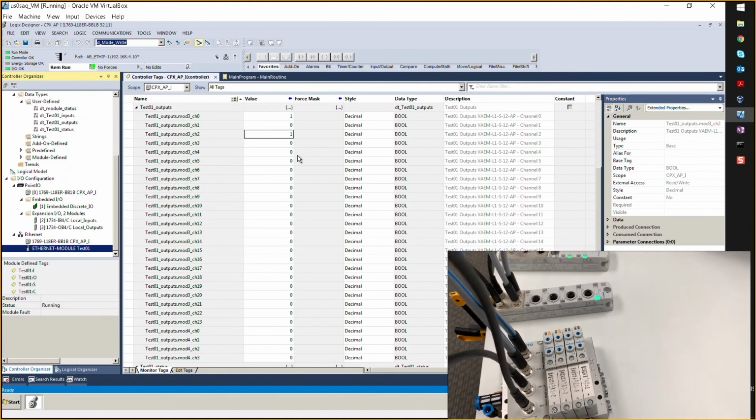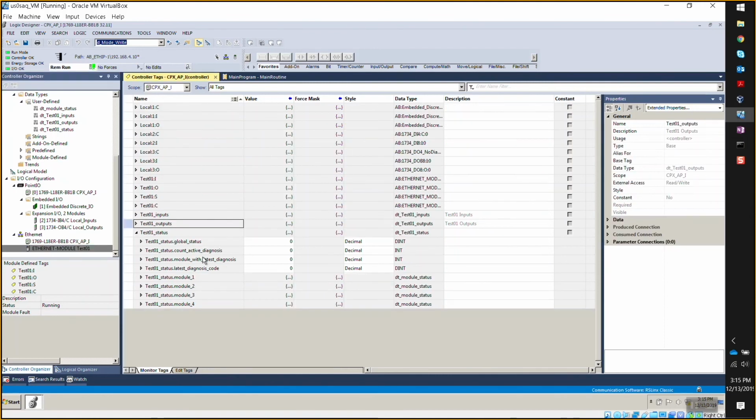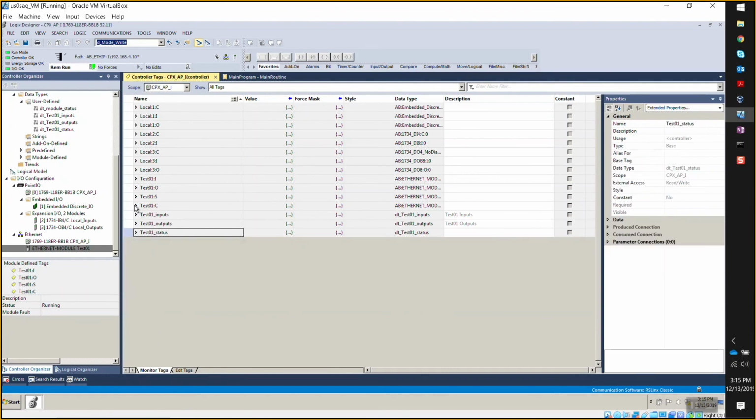Comparing it to the CPX, we don't have that modify Festo maintenance tool or... Yeah, we don't have that modify feature anymore, that system save parameter that we used to be able to use to save the parameter on a device. But this is a much more secure way because it's really excellent for disaster recovery. If something were to happen to the AP node, needed to be replaced, the parameters will always be there because it's pushed down from the PLC. It doesn't reside in the Ethernet adapter.